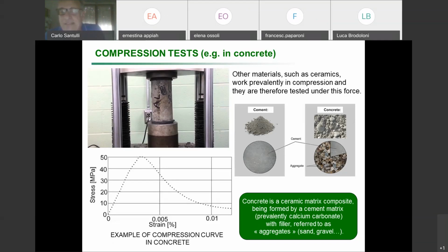over time, because you can imagine that there is also a kind of thermal fatigue. If I apply some cycles which are not just loading and unloading, but hot and cold, or warm and cold, so for example, a day and night cycle, this can allow the material to deform, to flow, because they are not really elastic. They are viscoelastic.